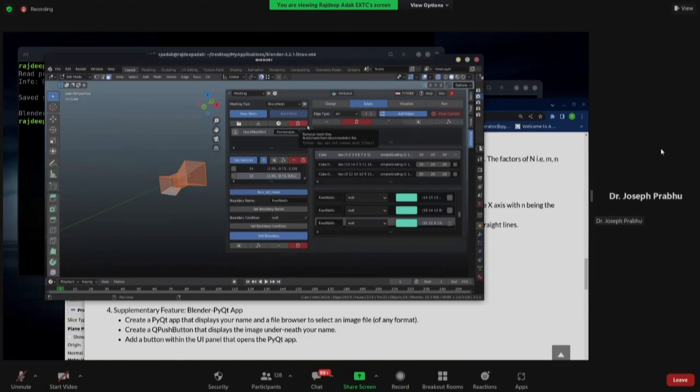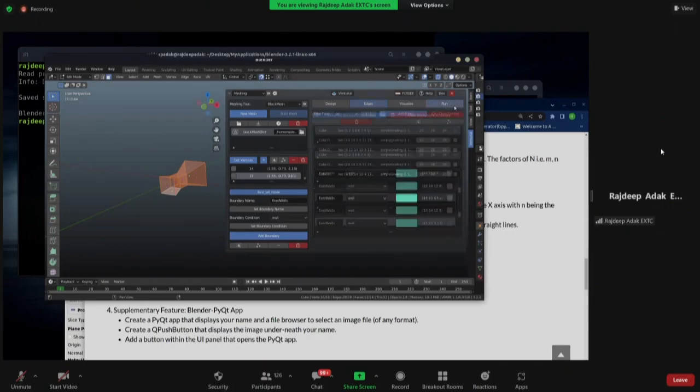Okay. Then we can generate the blockMesh file here and we need to run blockMesh and generate the mesh. Yes. In another developmental version, there is a run option over here, which works primarily on Linux. You click on that and it automatically does the job for you. You don't even need to type it. You can even open ParaView from within this. So that is also there.